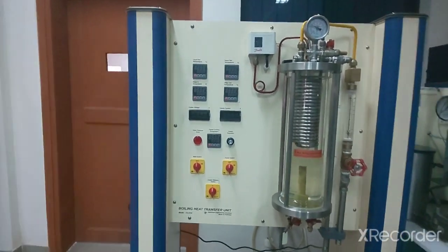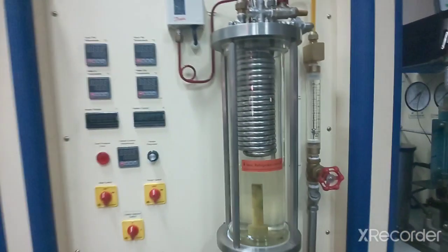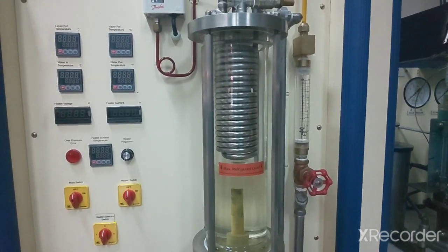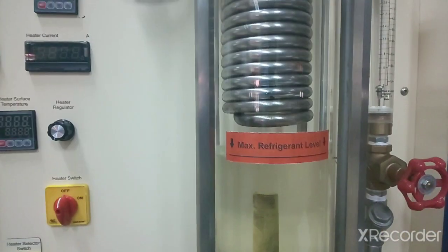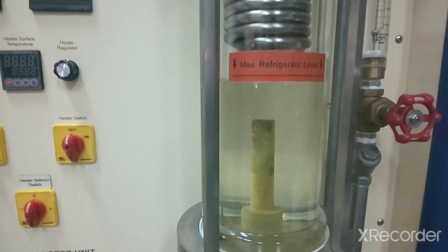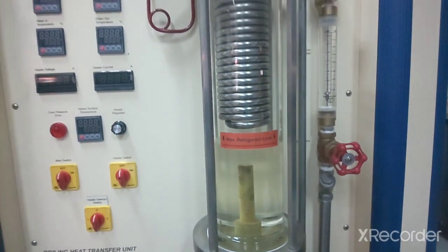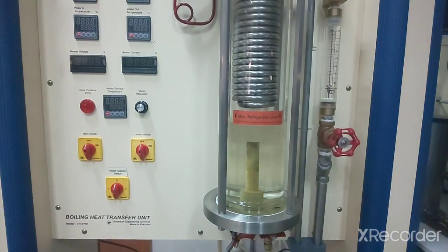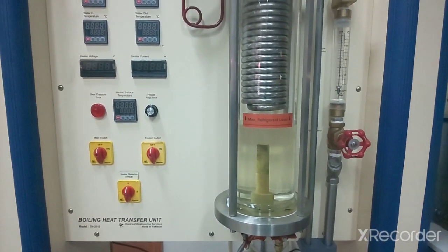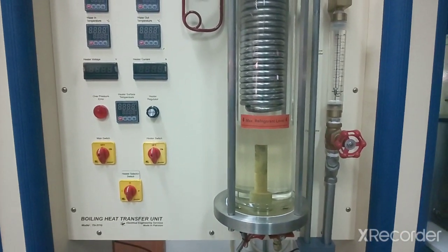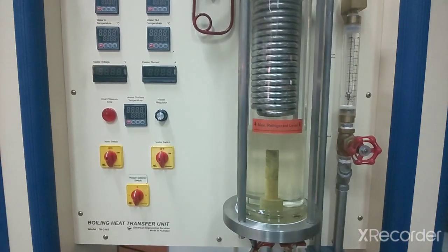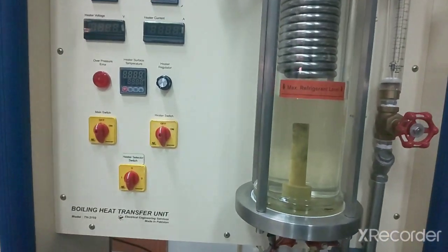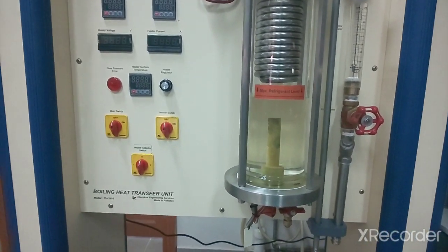Now coming to the apparatus. The most important part of this apparatus is this cylinder, in which we have a refrigerant. You can see the refrigerant is present in here. We have to maintain a certain level of the refrigerant. We are going to boil this refrigerant and see the effects of the boiling on it. It is basically R141B. You can search it out and find its specifications. Its standard boiling temperature is about 32 degrees Celsius. So we don't really call it a liquid, we usually call it a gas, but now it is in the liquid form at this temperature.